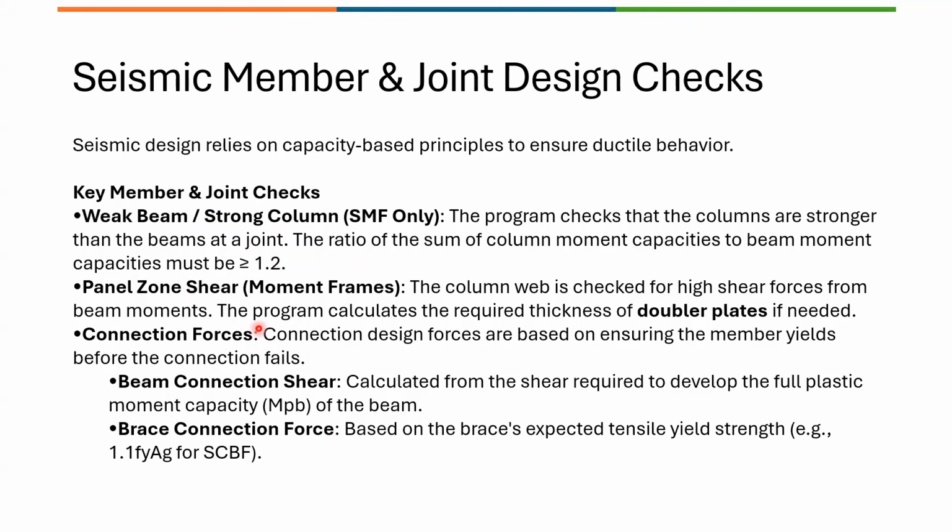And then panel zone, if needed, it can design the doubler plates and it will report the thickness. And if needed, the flange modeled as plates, the required area, the continuity plate can be designed and reported by the program, right, for SMF. And then it also reports the connection forces.